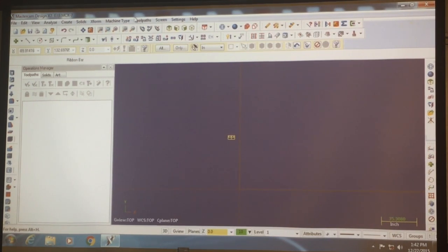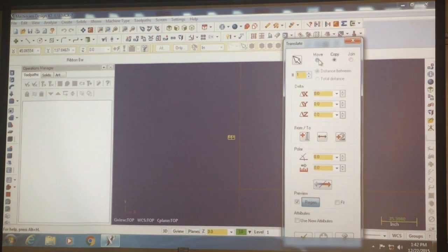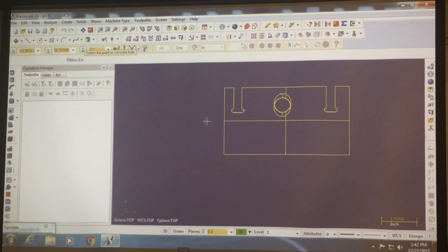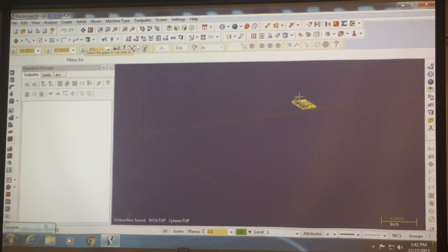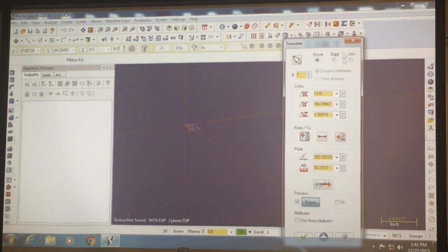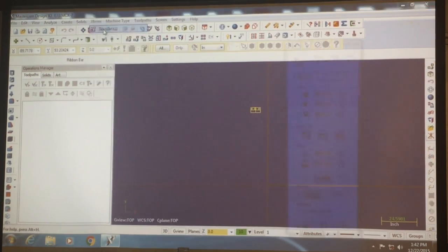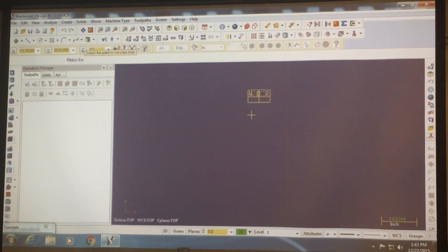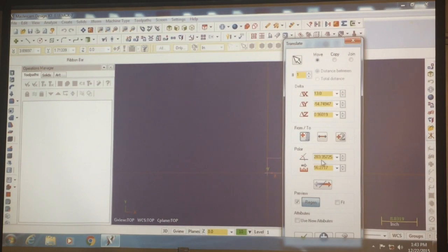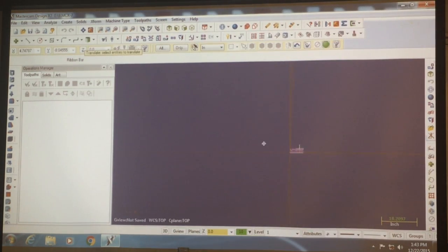So we're going to select it, we select X form, translate, and move, and we do from to, and we select this guy, and then we select our second point. Alright, I'll redo that so that you can understand what I'm doing. So right now it's up there. We select X form, translate, and move. Because if we select copy, it's just going to make a copy. And then we select this +1 here, which is the first point. And we're going to move it to the second point. All right, and apply.